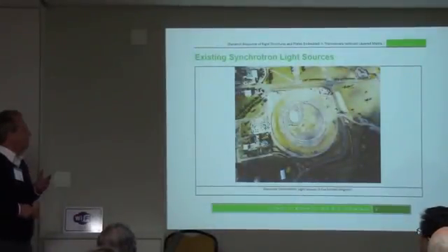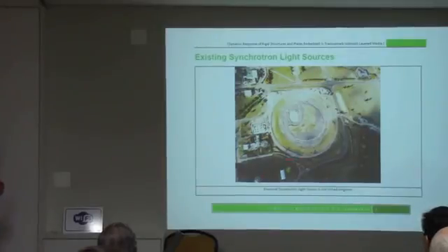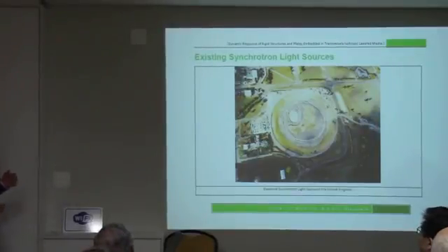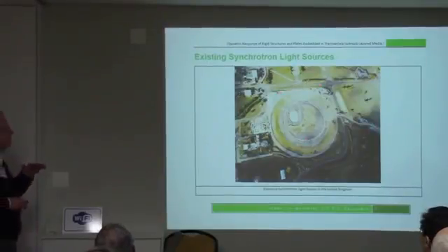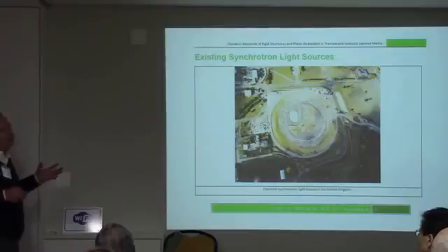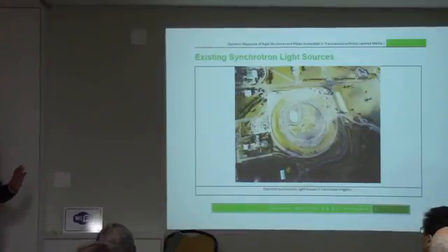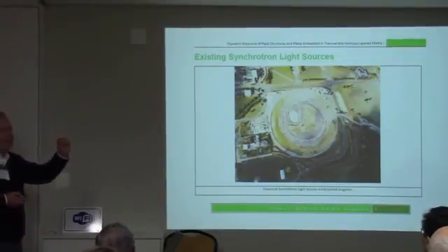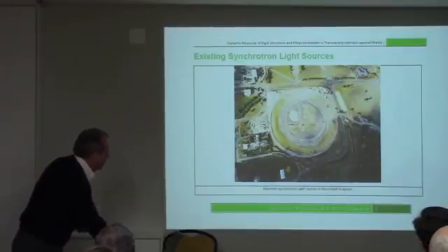So a typical synchrotron light source that's working well is the Diamond synchrotron in the United Kingdom. You can see here it's actually a forest of piles, and you put a concrete slab on it later on. I know that we talked to people. The Spanish did not use the pile foundation; they used only a raft there, and they have problems. It's not that it will not work; the issue is, if it vibrates, you don't get the necessary focus on the beam. So it will work, but if you really have a stable foundation, you have a more efficient system by having better focus on the light beam.